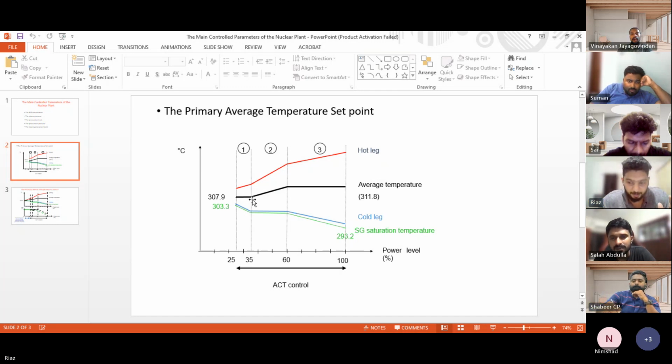If the turbine is rotating at the power needed, the reactor power will be equal, proportional to the thermal heat generated inside the reactor. Whatever the generator is producing will be directly proportional to the reactor power inside the RPV.